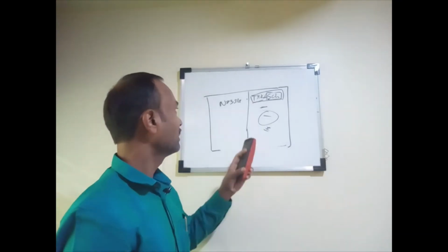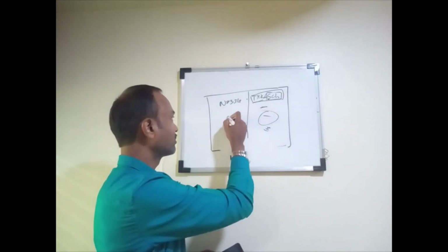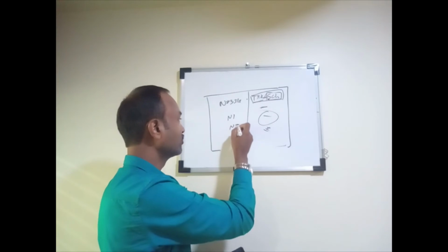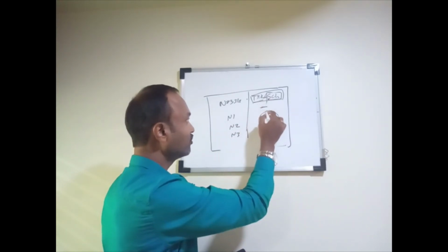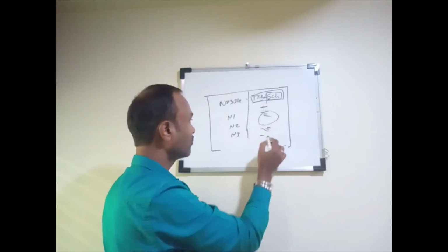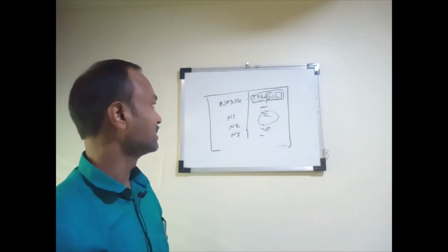In the nozzle table, for the nozzles we have taken, like EN1, EN2, whichever nozzles are there, for that we have to mention either what schedule we have taken, or what thickness we are taking for that nozzle. So many times this is missed.